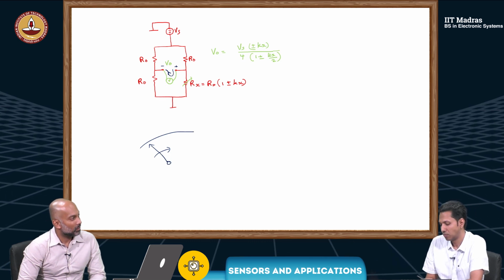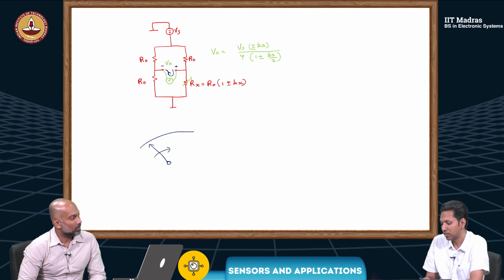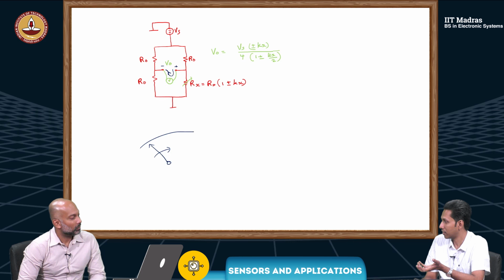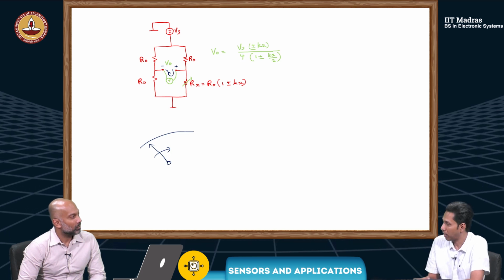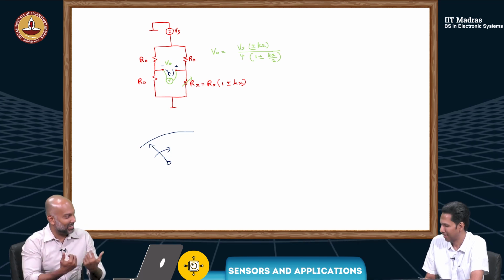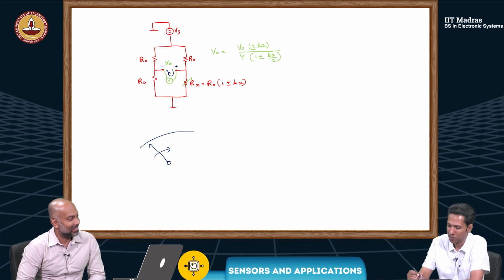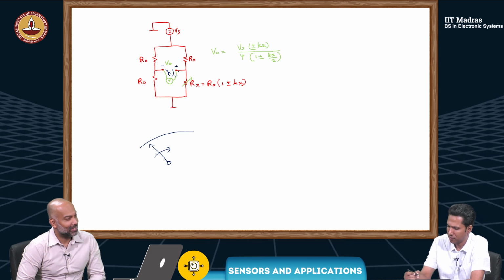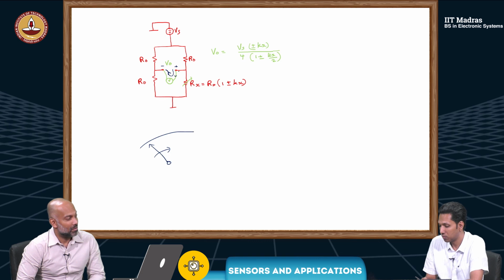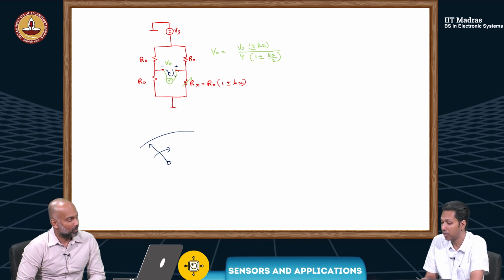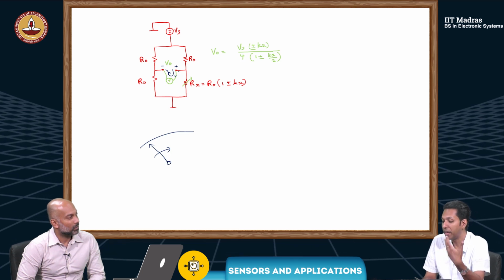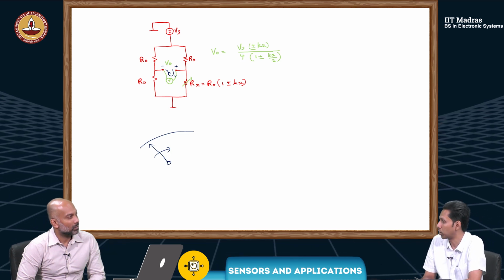There, essentially, the work it is doing or the energy for it to display has to come from the measurement. So it's drawing some current here. Definitely, it will be drawing some current. So that will not be negligible. Yes, so you need to consider that. So that may not be an option. So we will need some instrument that gives very high input impedance.